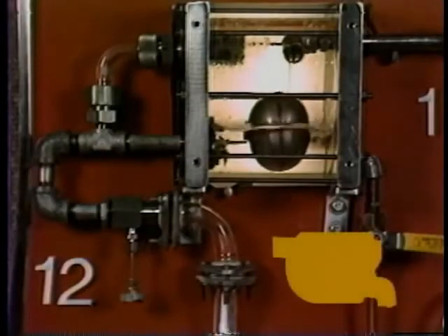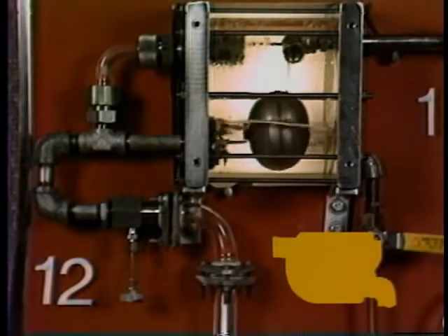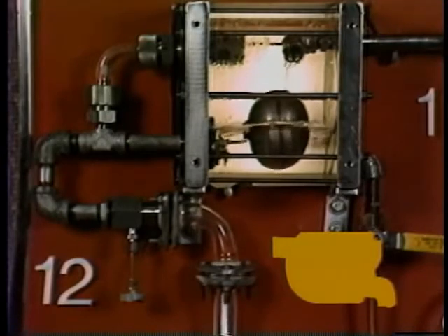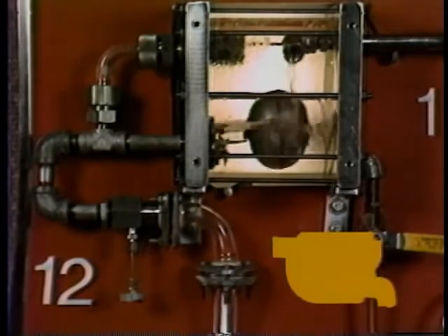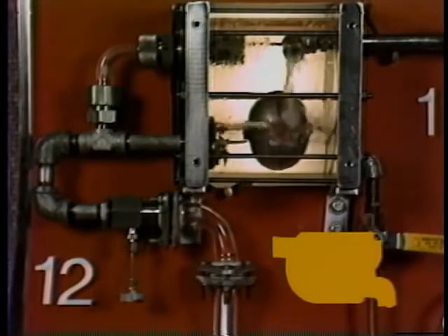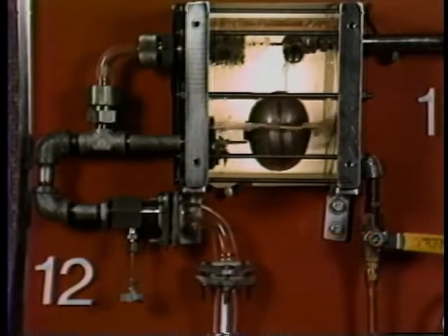The F&T trap is most often used on modulating systems because it is a continuous drainer that handles startup air loads and light condensate loads well. It may have a good service life if caution is taken to prevent damage to the trap in systems where dirt, freezing, and water hammer are likely to occur.